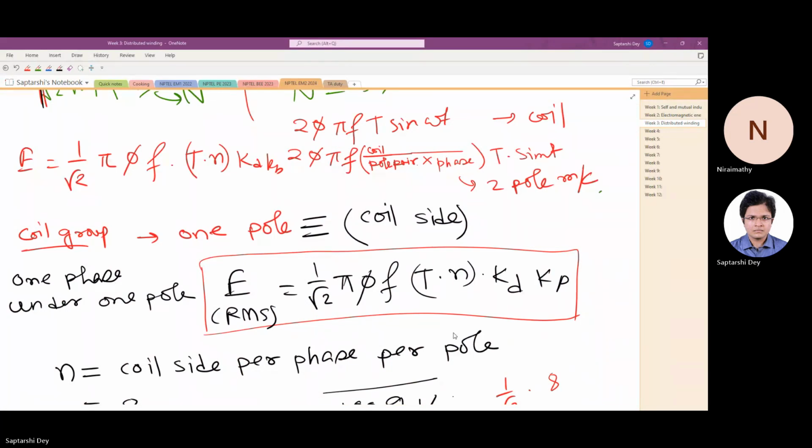How do you measure the temperature of the motor? Nowadays, there are thermal cameras. Are you saying online measurement, like for tripping on short circuit? Yeah, online. See, if it is that critical, you can have temperature sensors inside the motor. In general, it's the other way around. It's designed so that it's always inside the safe temperature range. But still, if you need thermal protection, then you can have sensors inside.